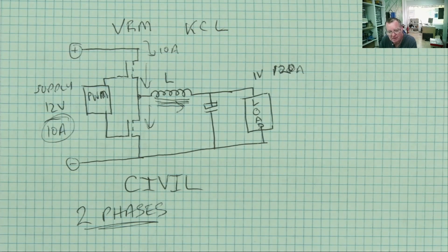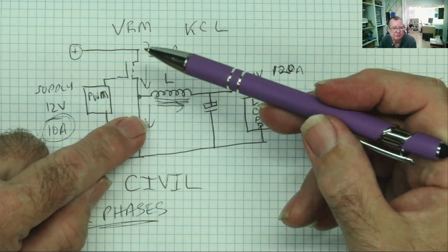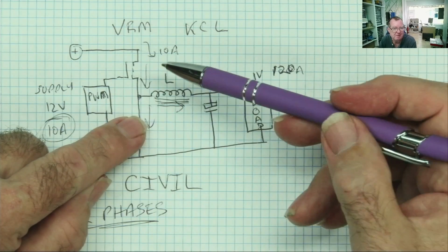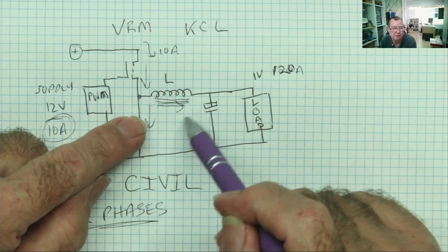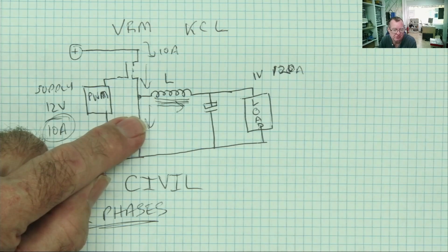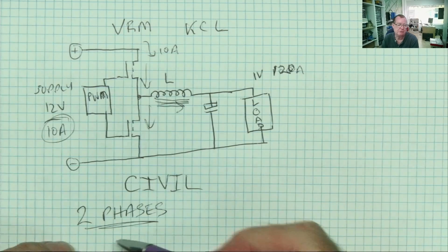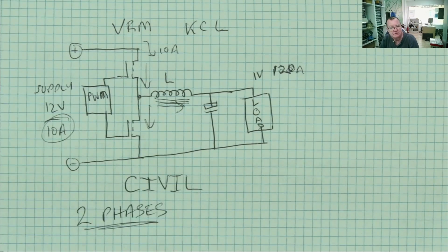And you may, if you think about it, wonder, why do we need this MOSFET? Why can't we just keep pulsing this one at high frequency with a pulse of just the right width to give us just enough magnetic field in the coil, so when it collapses, it powers the load and charges the capacitor? Well, the reason for that is also the fact this circuit has two phases. So let's have a look to see what actually happens. In the first phase, we magnetize the coil.